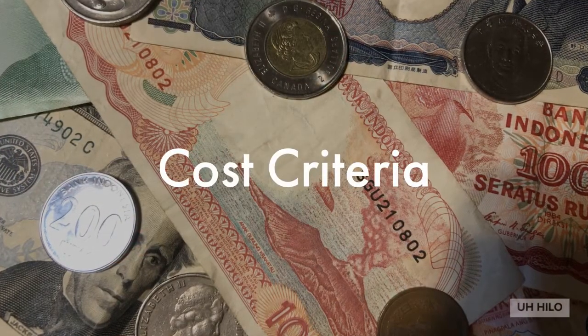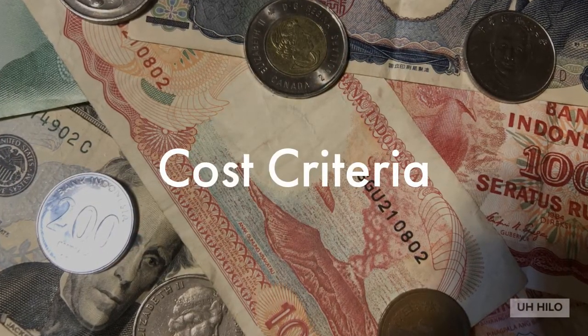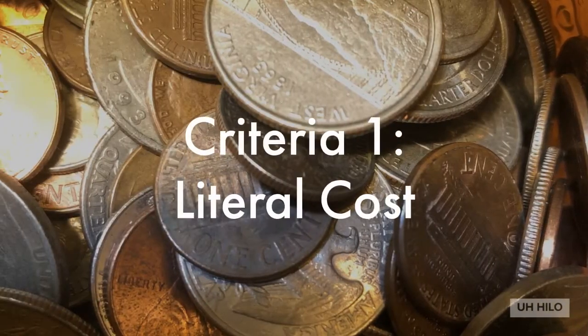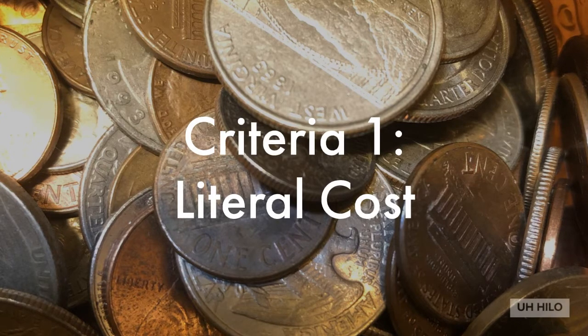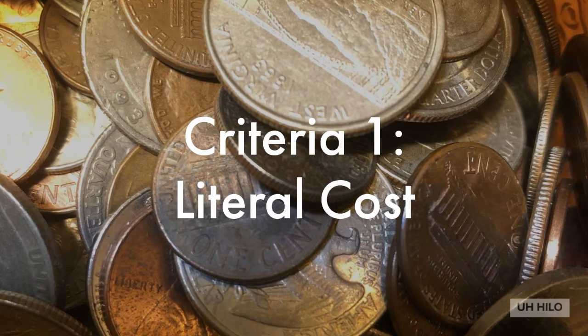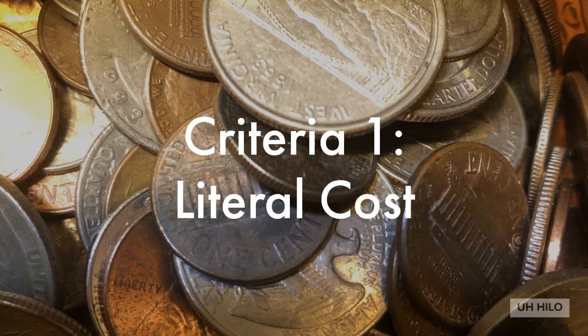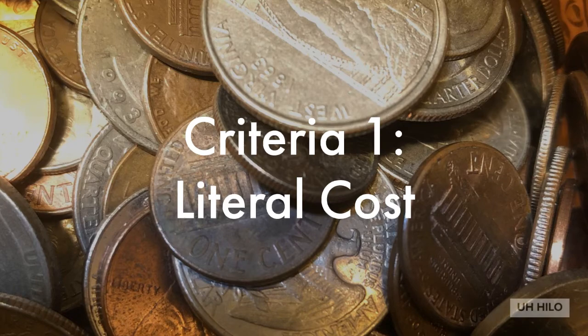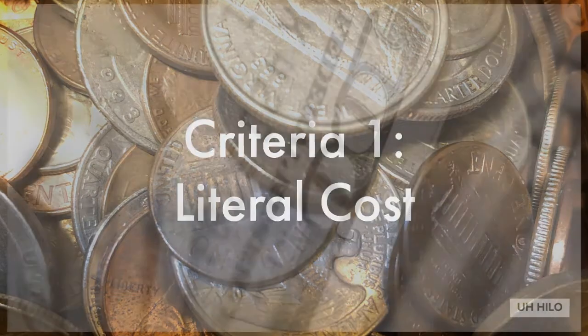Before getting into the nuts and bolts of the maps, let's take a look at cost criteria for constructing a circuit. Literal cost is the number of literal appearances in a Boolean expression. This is simple, but not always accurate. 2 circuits could have the same number of literals, but one could have 2 terms and the other could have 4. That would mean vastly different costs for the 2 circuits.